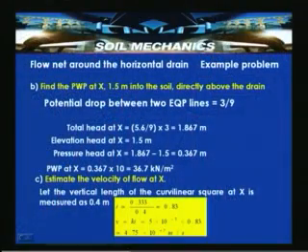From that we can see the velocity of the flow at x is given by 4.75 × 10 to the power of minus 7 meter per second. So, in this problem what we try to do is to determine the seepage or discharge through the pipe per meter length, and then by treating the long horizontal drain as a two-dimensional problem, we constructed a flow net and it has two flow regions.